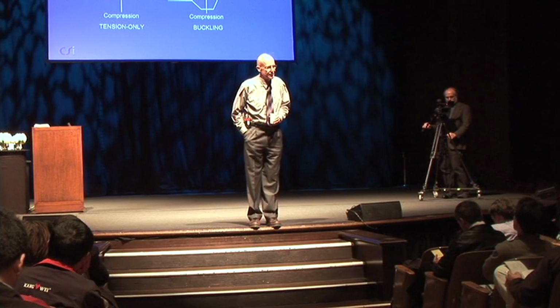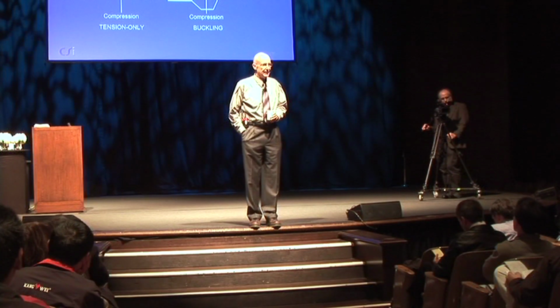But when you start the design and you are saying it doesn't work, what do you mean it doesn't work? The question is, is it a reasonable model for you to use for your nonlinear analysis? If you feel it's a reasonable model to use a chord rotation model, then I'd say use that. If you don't think a chord rotation model is reasonable for some reason or another, then take a look at a plastic hinge model. If you feel that is not reasonable for one reason or another, then take a look at a plastic zone model and just work down the hierarchy. Sooner or later, though, you've got to make a decision. It's got to be made.